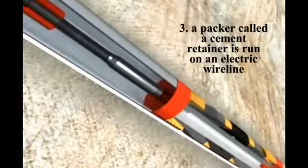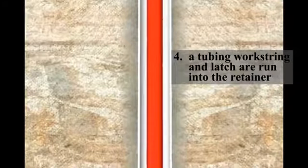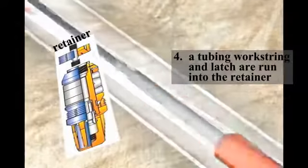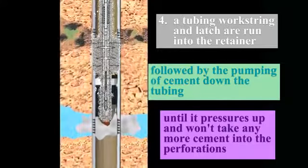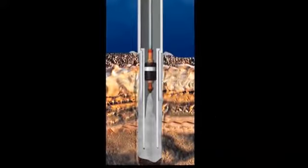Third, a packer, called a cement retainer, is run on an electric wire line and sets the retainer above the old zone. Next, a tubing work string and latch are run into the retainer, followed by the pumping of cement down the tubing into the pay zone until it pressures up or won't take any more cement into the perforations. This is called squeeze cementing.